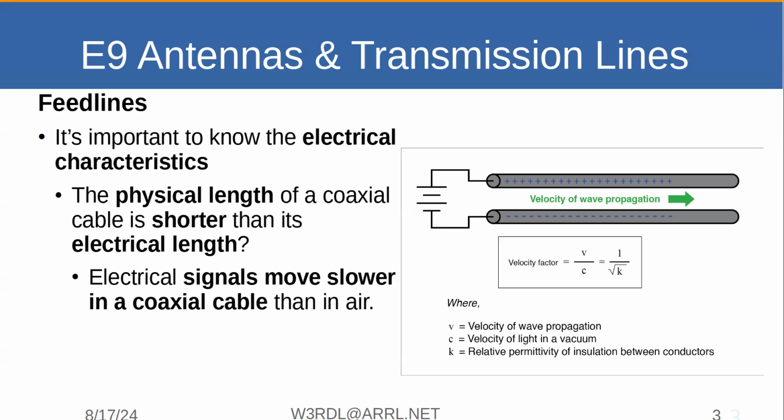Yeah, that's called a TDR function, time domain reflectometer, where you send out a pulse and then you measure how long it takes to come back. And that will tell you the electrical length, not the physical length. So you have to really know. But a NanoVNA should be able to do that too. I know you can do the TDR. I found out which end of my coax cable was shorted by doing that.